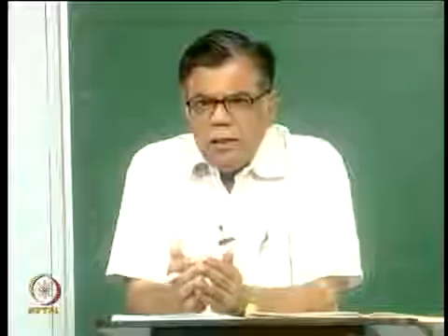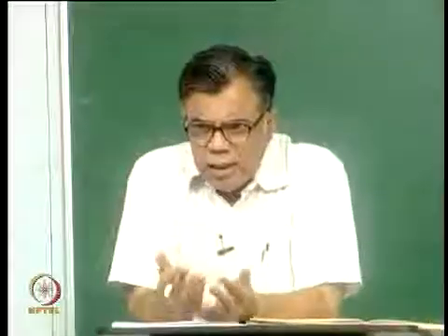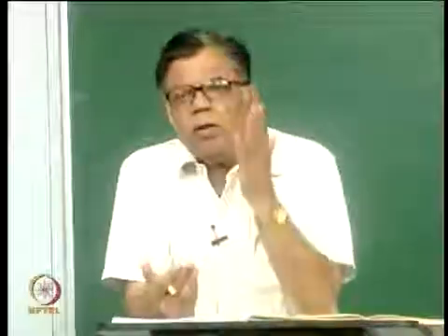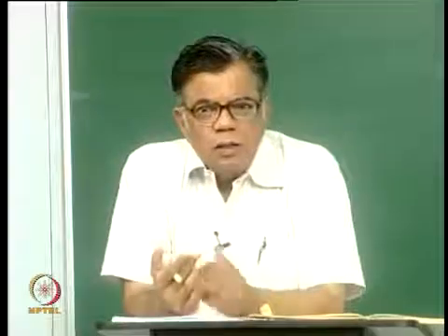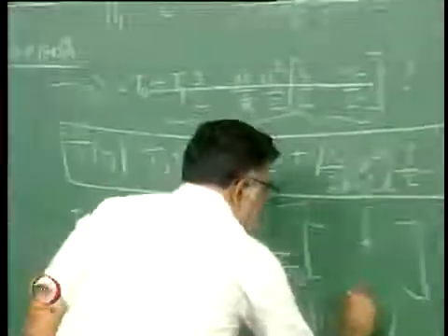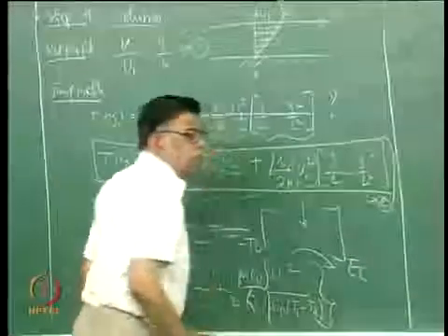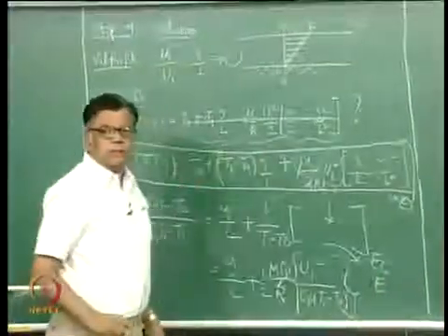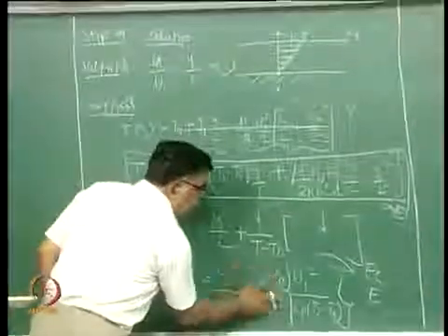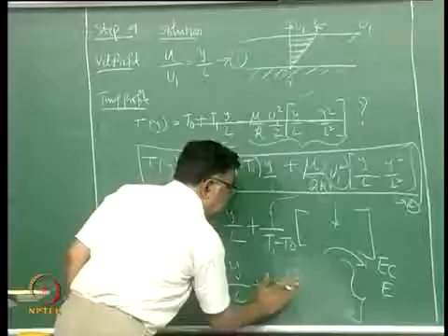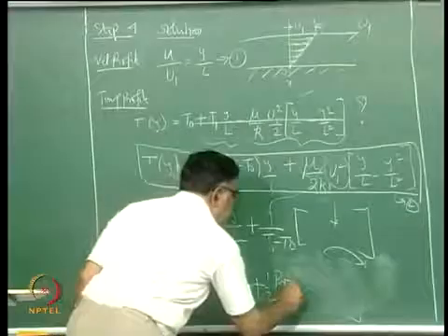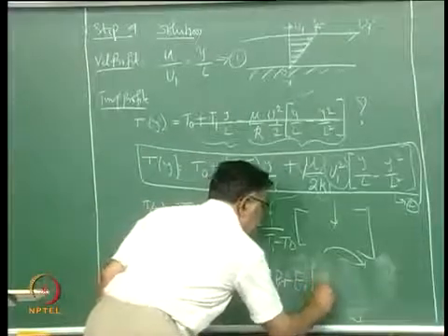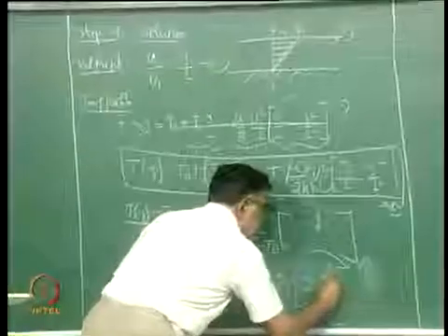So in this problem there is a certain energy in terms of Cp T that is now being related to the velocity of the plate. If the plate were stationary, it would not have come up. In fact, that would be 0 obviously. So a new number has come up now called Eckert. Some books give you the symbol as EC, some give you the symbol E, use as you like, but now you just change the final equation as y by L plus half Prandtl Eckert into y by L minus y square by L square.